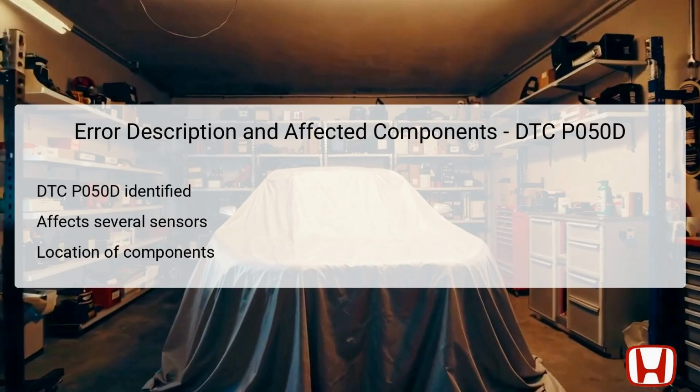DTC P050D is specifically related to the cold start idle speed issue, which directly affects the vehicle's drivability. The powertrain control module, PCM, monitors signals from several components, including the engine coolant temperature, ECT, sensor, mass airflow, MAF, sensor, and intake air temperature, IAT, sensor. Each of these sensors plays a crucial role in accurately providing readings to the PCM, allowing it to manage the fuel-air mixture and ensure appropriate idle speeds during cold starts.